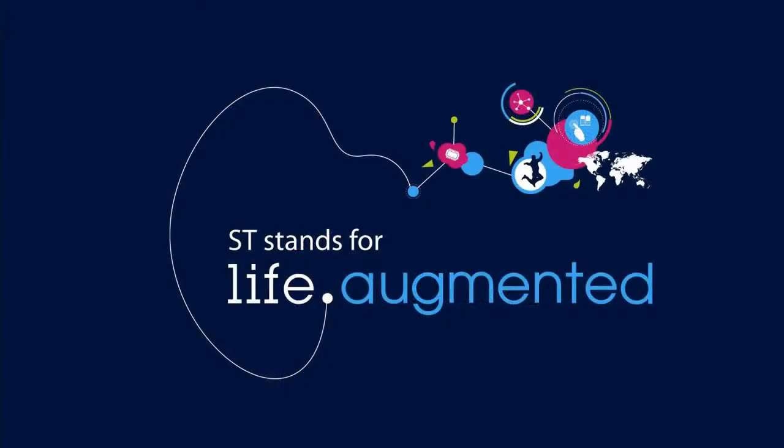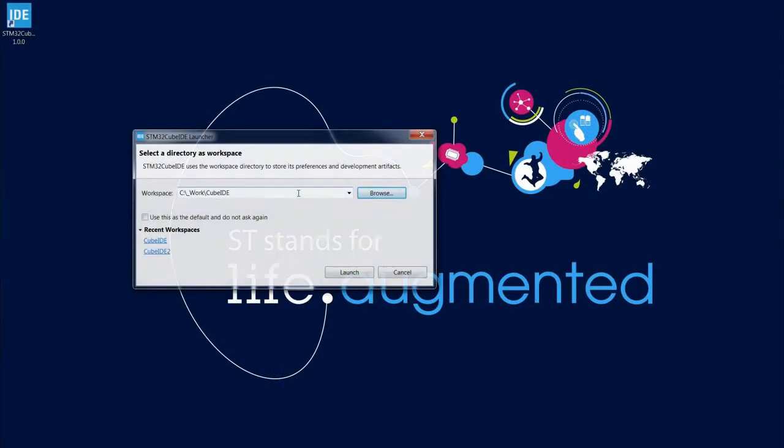Let's open the CubeIDE application. The first thing we need to do after running this application is to select the location of the workspace. I would select a different name just to start everything from scratch. In my case, it will be C, then underscore work, and subfolder CubeIDE, but with number 3.